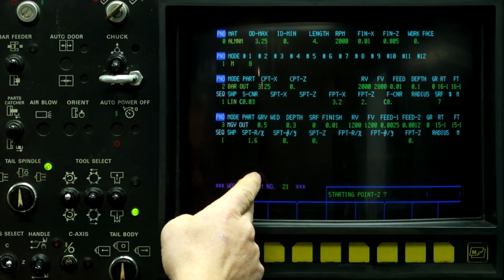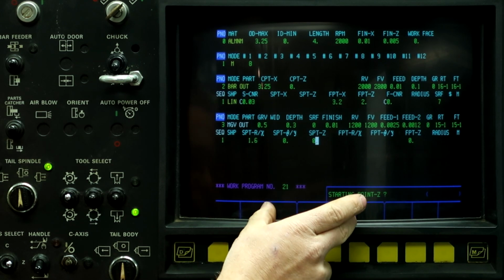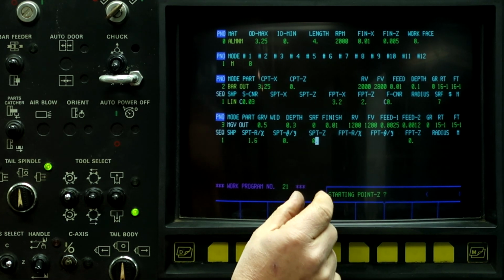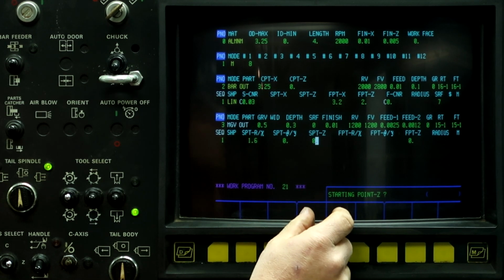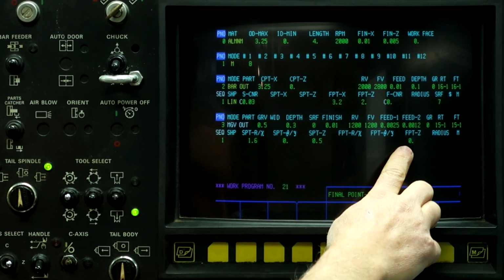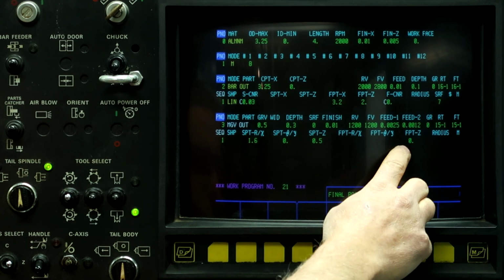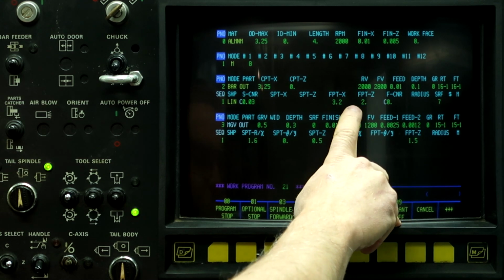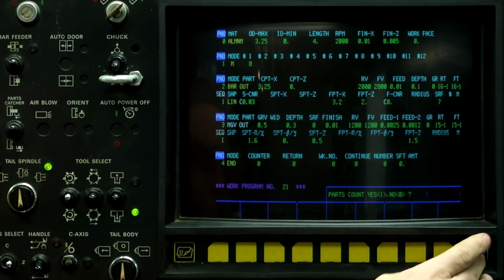From the center line of the slot is what this is programmed with on Z, to the end of the part is a 1/2 inch in distance. Minus 1/2 the tool is going to give us a 250 dimension at the end of the slot. Final point on Z, I'll go 1.5, and then it'll have a 1/4 inch off the end of this. And then we'll say end, and now we'll take a look at it.